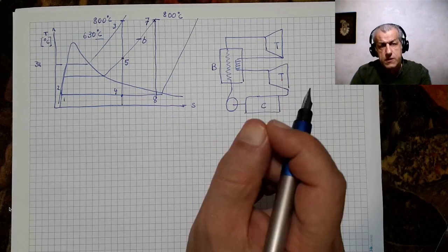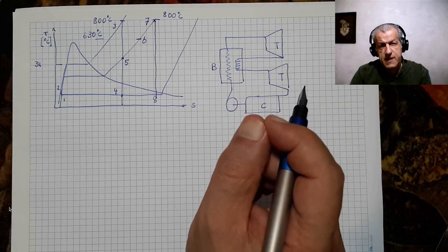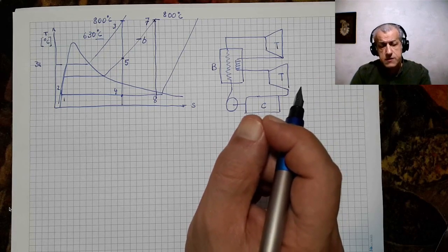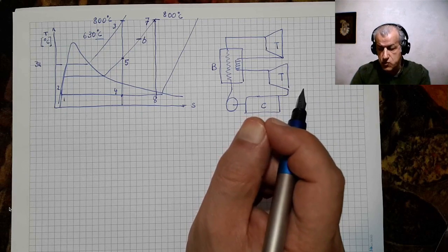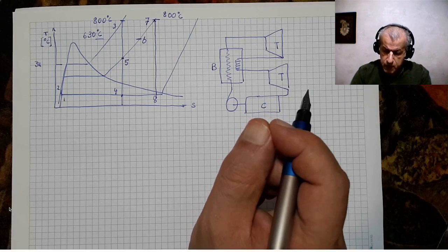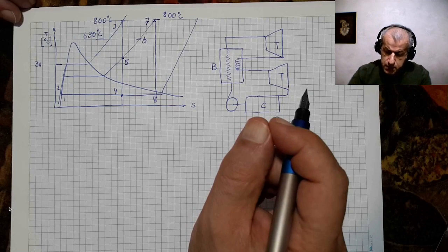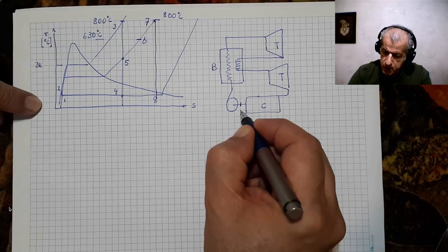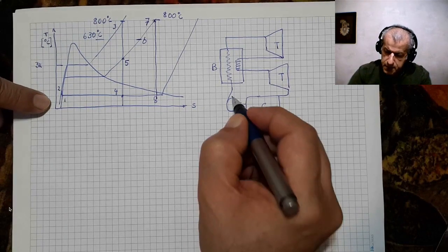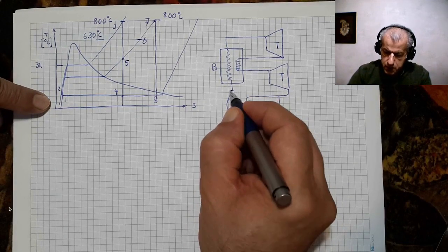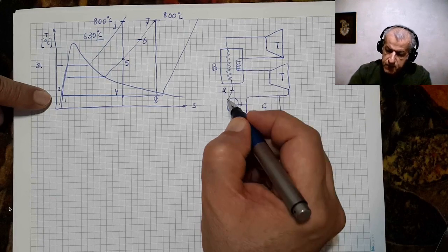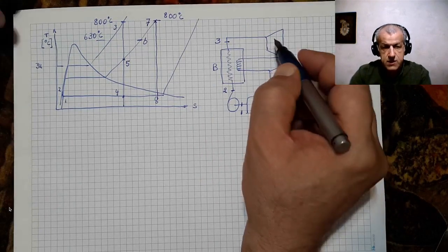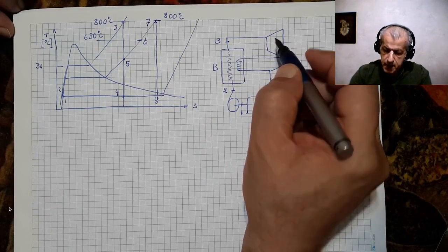Well, now, the first step to solve such problems and all the cycle problems is to find the points, find the properties. That's a very important first step, and it's a very time consuming first step that we should do one by one. If I try to put these numbers on this figure, this is point 1, which is entry to the pump. This is point 2, the pump exit. This is point 3, the boiler exit and entry to the high pressure turbine.